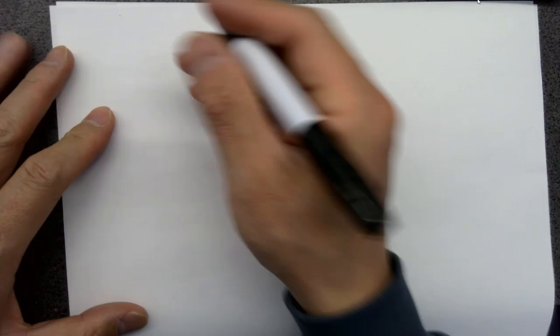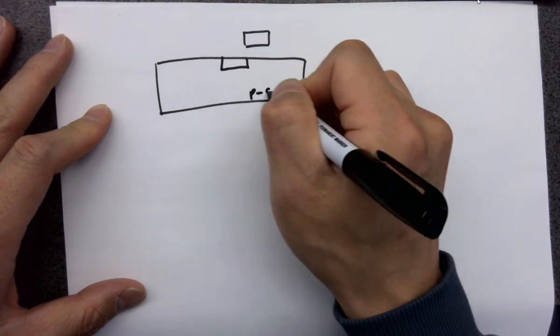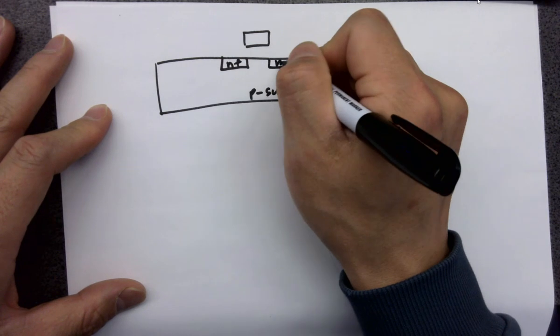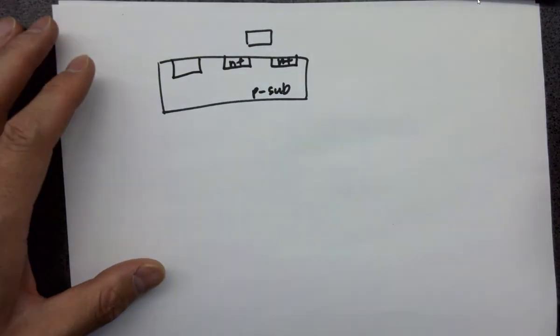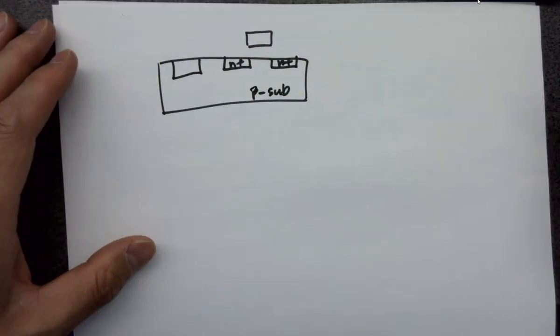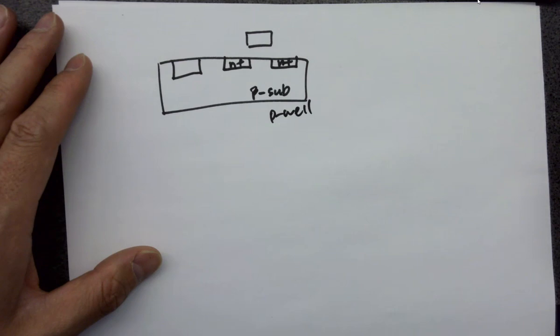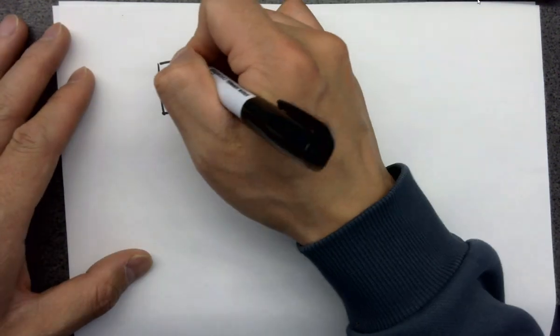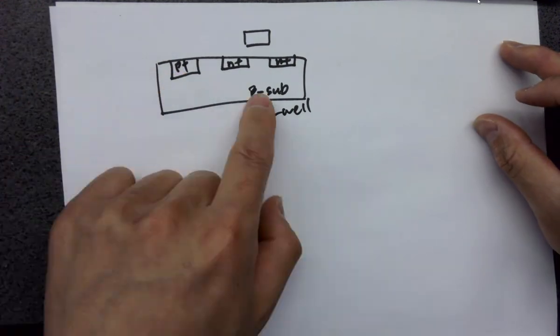Body effect. For NMOS, that's a P sub. Okay, so we need a well tap, even though there's no physical well, but the P sub, the whole wafer, is considered as a well. It's called P well. So you need a well tap in order to make the connection to the well. P plus is a P sub well tap,